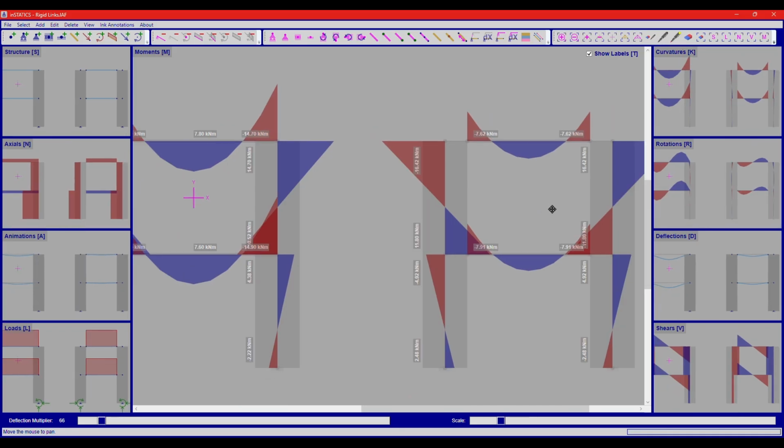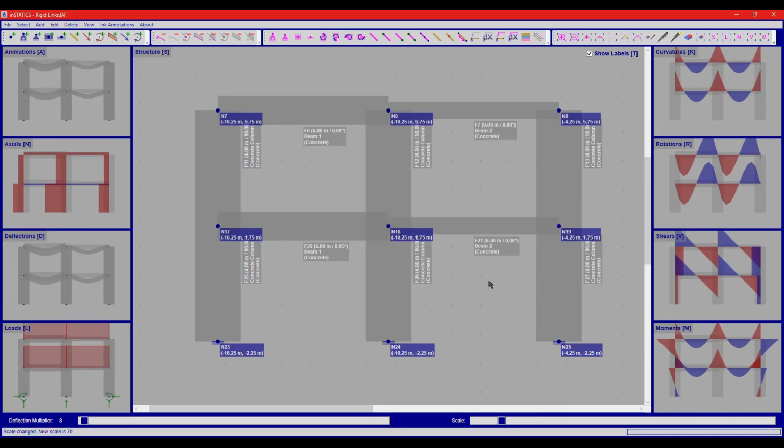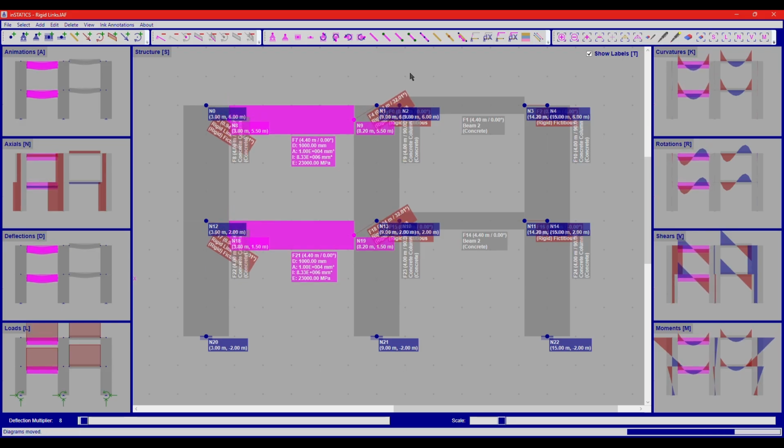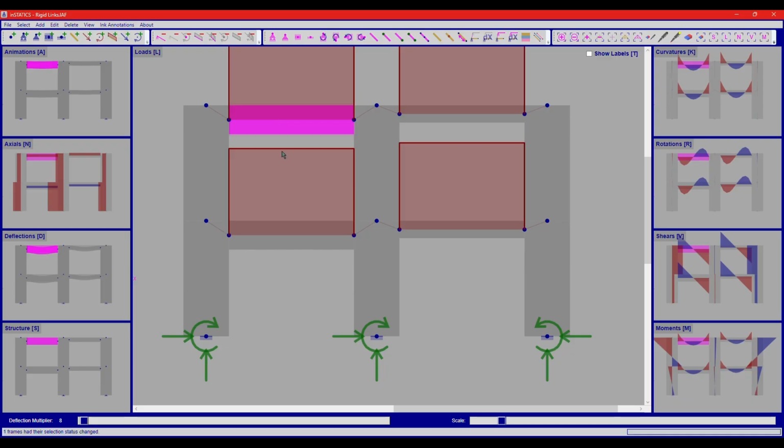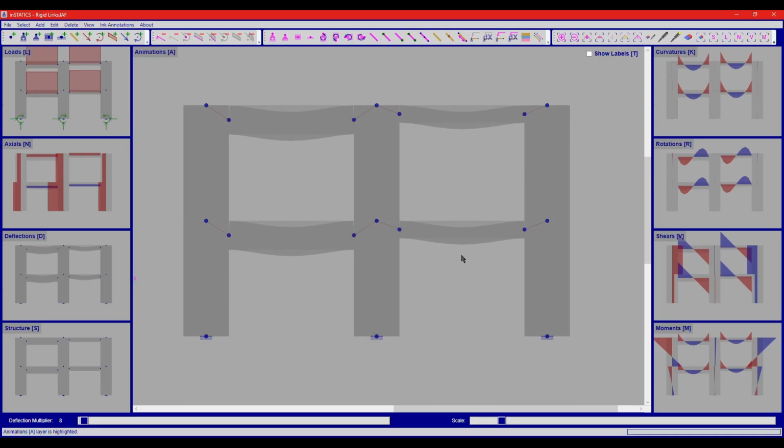Another limitation of one-dimensional frame elements is the inability to position deeper beams of a structure flush at the floor level. Assuming the nodes are located at the floor levels, none of our beams are positioned properly here. We can use rigid links to resolve this issue as well.